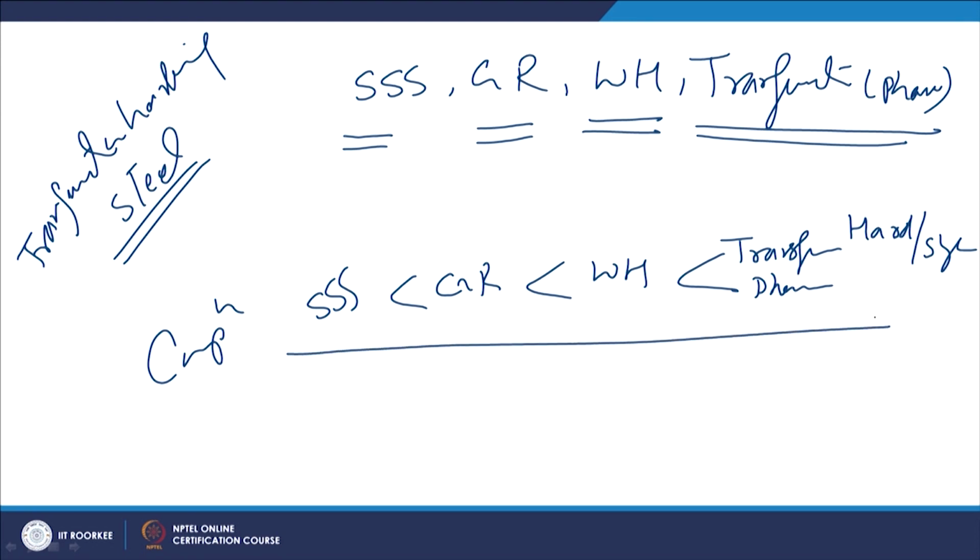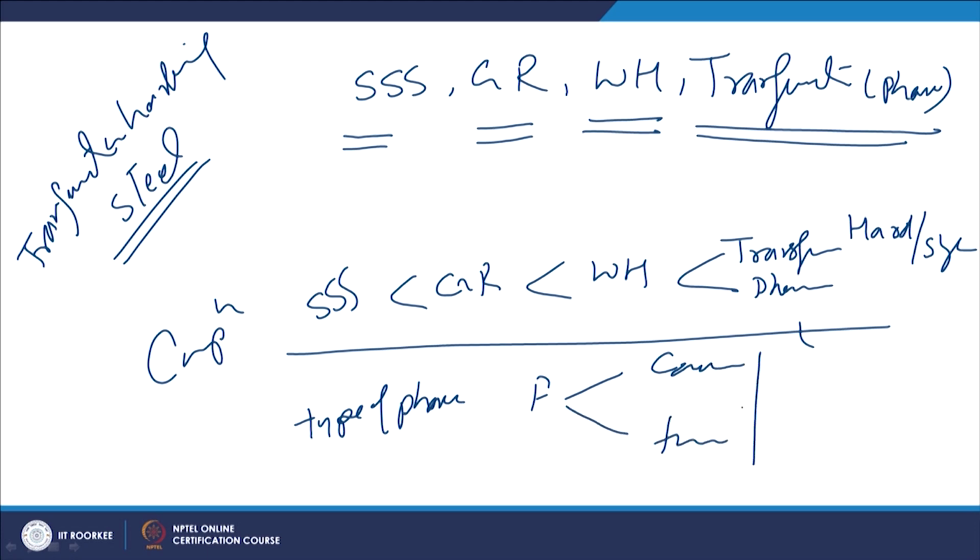And that is why sometimes we will notice that if the type of phase is the same, like say the ferrite, and if the ferrite is coarse in one case and fine in the other, then of course the fine ferrite will lead to better properties as compared to the coarse ferritic structure. But if the metal has been subjected to annealing and the same has also been subjected to work hardening, then the work hardened metal will offer better properties as compared to the annealed one, even if there is no change in the phases.